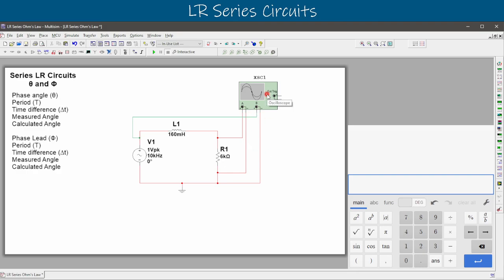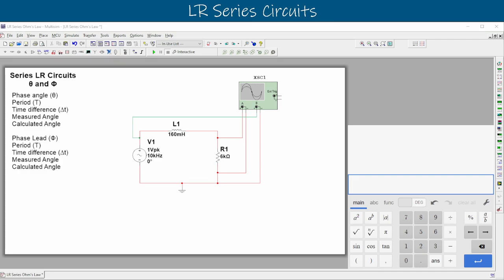Now we have our voltage source off the front. Measuring around there, we can compare those two, our voltage to our linear resistance, right? Because if we were to measure across our inductor and our resistor and compare the voltage drops between those two, we should find that they're 90 degrees apart because the linear resistor is 0-degree phase and the inductor is 90-degree phase. We'll find capacitors at negative 90-degree phase, right? So now that we have this set up, we can measure our period on our oscilloscope.